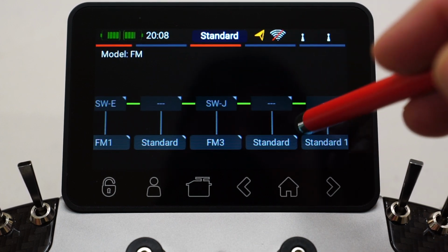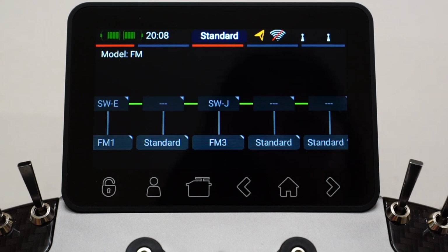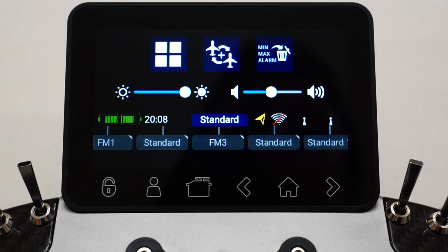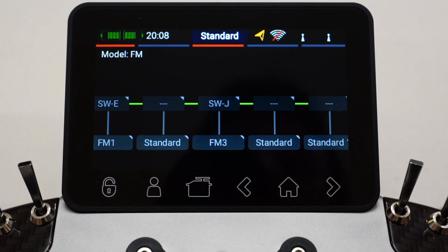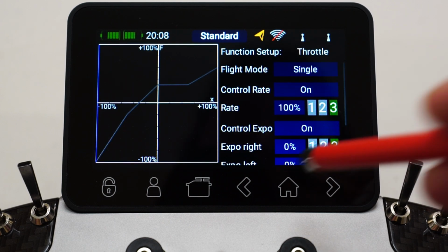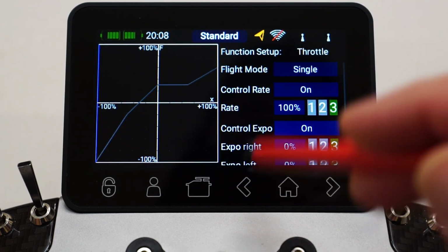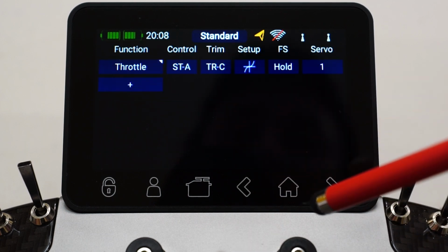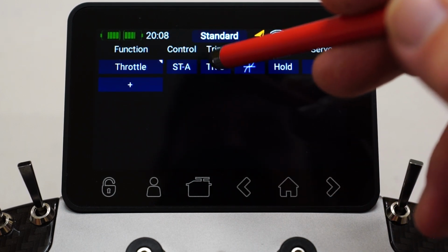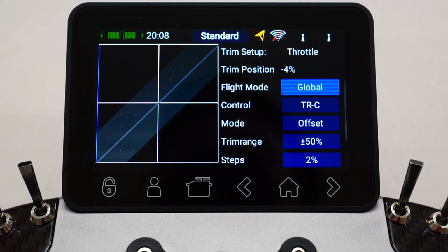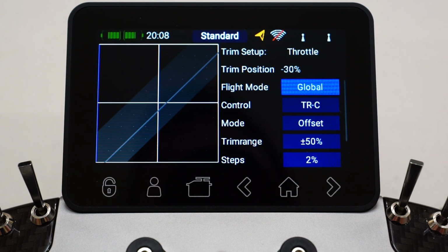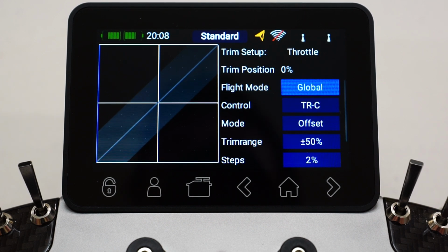Okay, now probably one other thing before we sign off is I haven't mentioned another handy feature with flight modes. Actually I'll better show you this as well, but before I do that, let's talk about trims, because I want to mention trims here. So typically, you have a trim. This one, I've just set up a default trim here, nothing too special. You can see I'm just holding down my trim lever. I don't have any audio selected, so it's nice and quiet. You can see it's moving the whole curve, only because I've told it to move the whole curve.